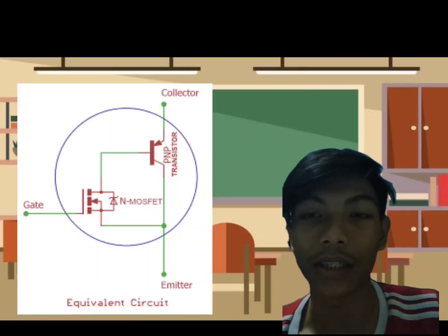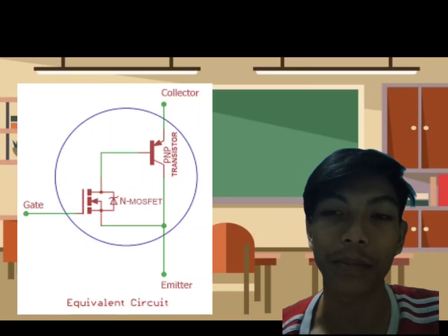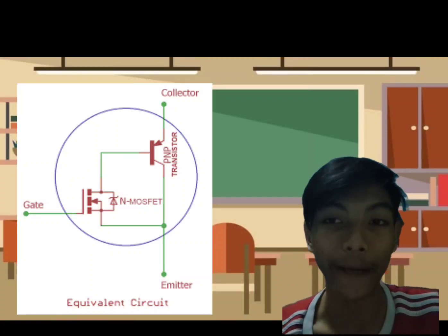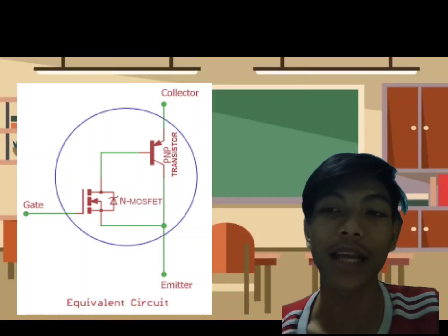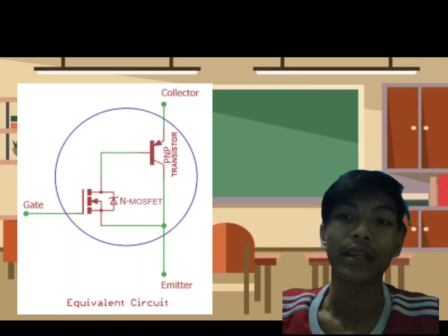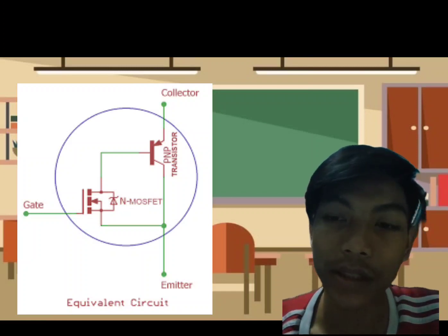Insulated gate bipolar transistors are mainly utilized for switching purposes. It consists of four alternating PNPN layers that are controlled by a metal oxide semiconductor gate structure. Properties of IGBT are negligible loss at the input and high power gain.